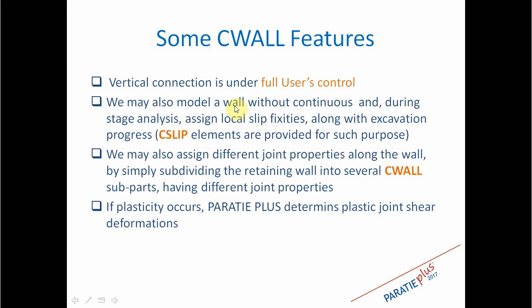For example, you can also omit the joint slippage internal to the element, but you can add later on during excavation analysis some special elements that fix this slippage at some points along the wall.